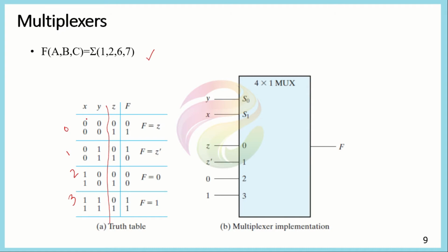So it means that for the combination of 2 selection lines of 0, 0, we could have 2 more combinations added to it depending upon how we choose the value of Z, which could be either 0 or 1. So one combination is extended to 2 different combinations depending upon the value of Z. One would become 0, 0, 0 and the other would become 0, 0, 1.